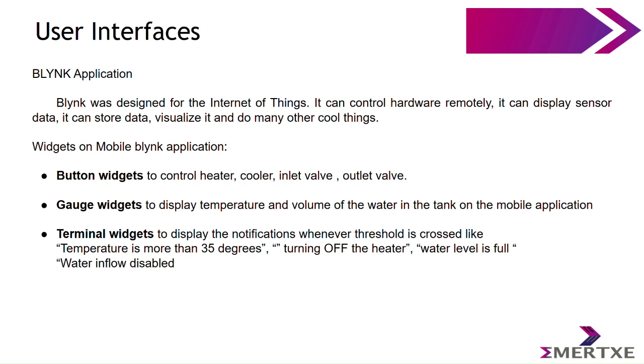Widgets on the Blynk mobile application. Button widgets control the heater, cooler, inlet valve and outlet valve. Gauge widgets display temperature and volume of the water in the tank on the mobile application. Terminal widgets are used to display the threshold which is crossed, like temperature is more than 35 degrees, turning off the heater, or water level is full, water inflow disabled.